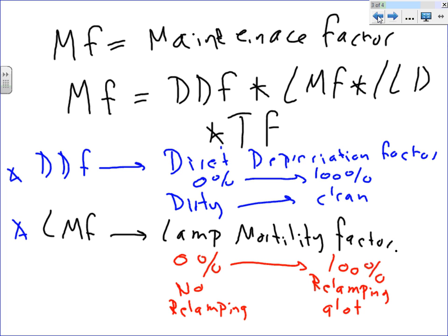This is one thing you have to explain to the customers as you walk in. They might be pissed off at you, very bright in certain areas. You have to explain why it's brighter than 80-foot candle: we took into consideration the maintenance factor, meaning we want to guarantee you this 80-foot candle 6 months, a year from now.